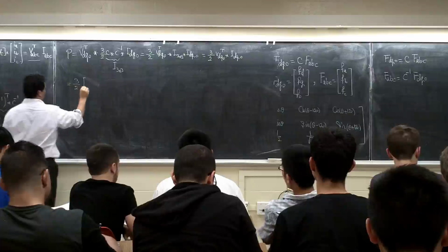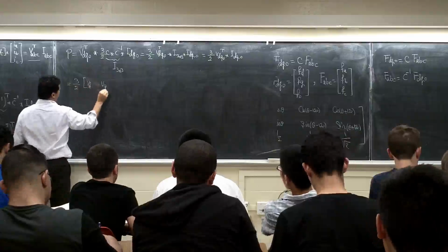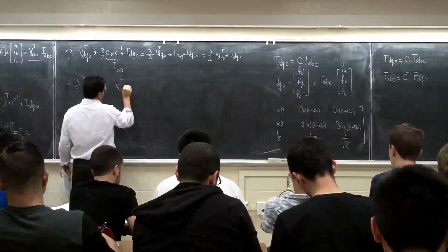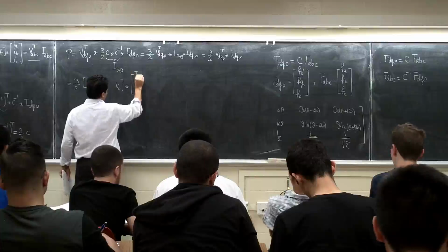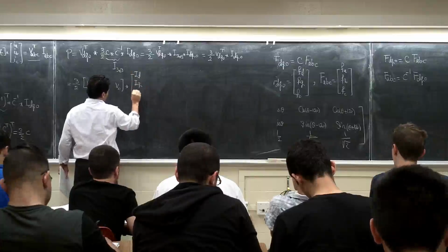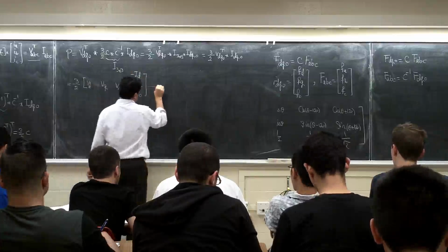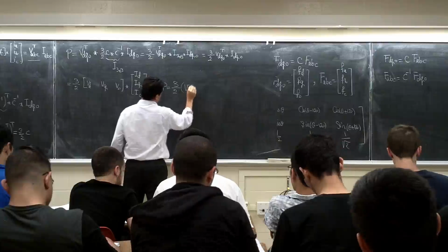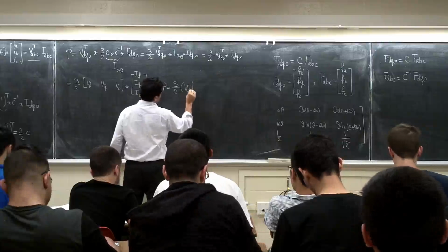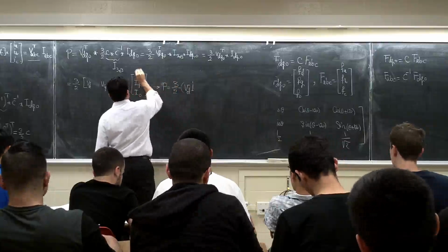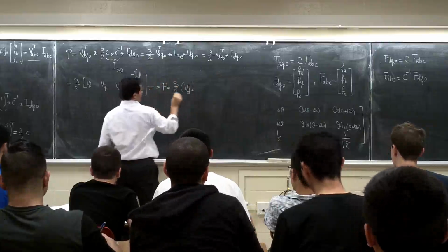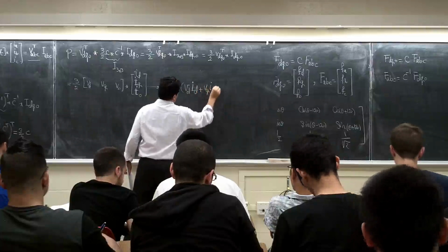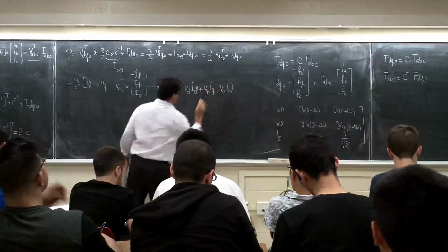VDQO transpose is going to be like VD, VQ, VO, times ID, IQ, IO. So basically P is going to be 3 over 2 times VD ID plus VQ IQ plus VO IO.